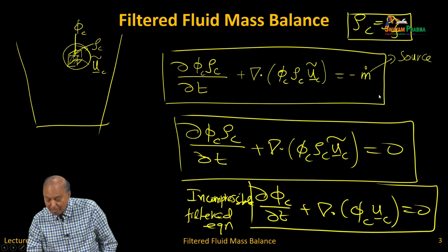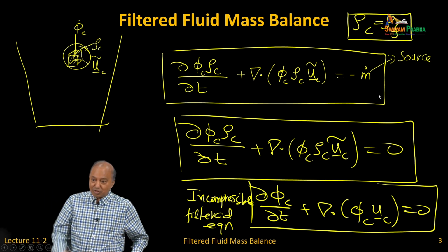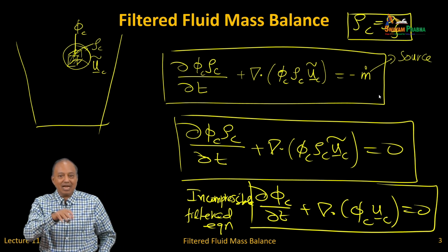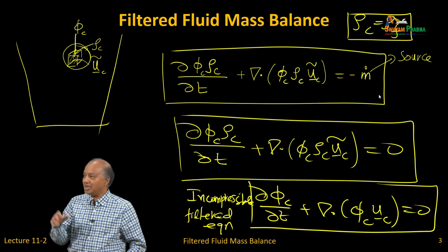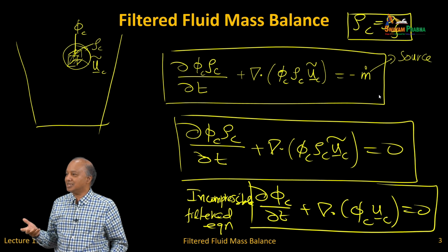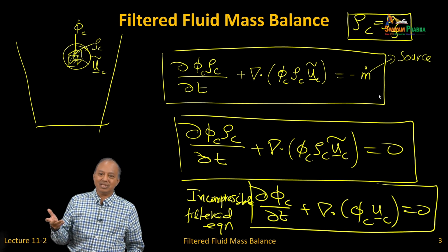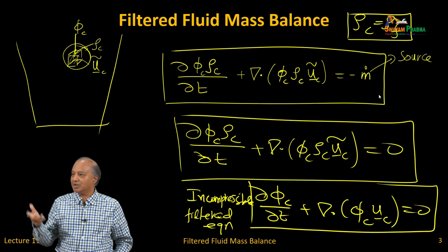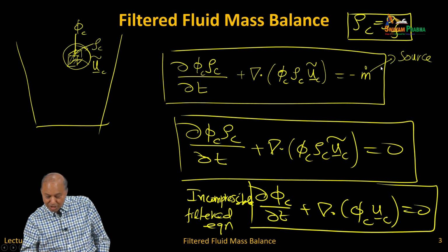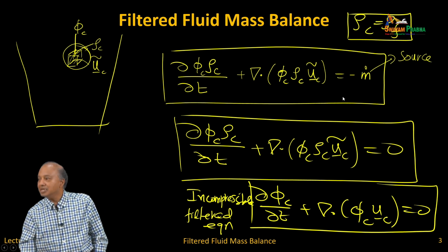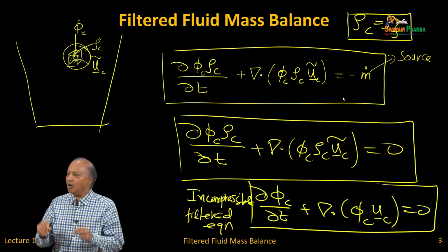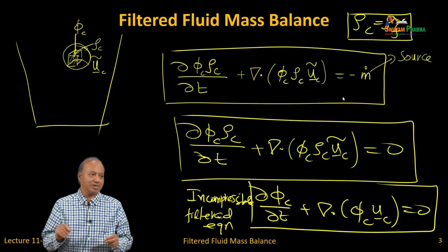Now, it needs to be modeled. In a particle resolved simulation, you will have flow around it, you can calculate the evaporation rate, condensation rates, everything you can precisely calculate. Now, all you know is that there are a bunch of particles inside, and you have to come up with a model for the evaporation rate of these droplets, or condensation rate in case of rain formation, etc. So, in other words, this is one modeling that needs to be done, and every time you will find that what we need to model is how the fluid is talking to the particles.